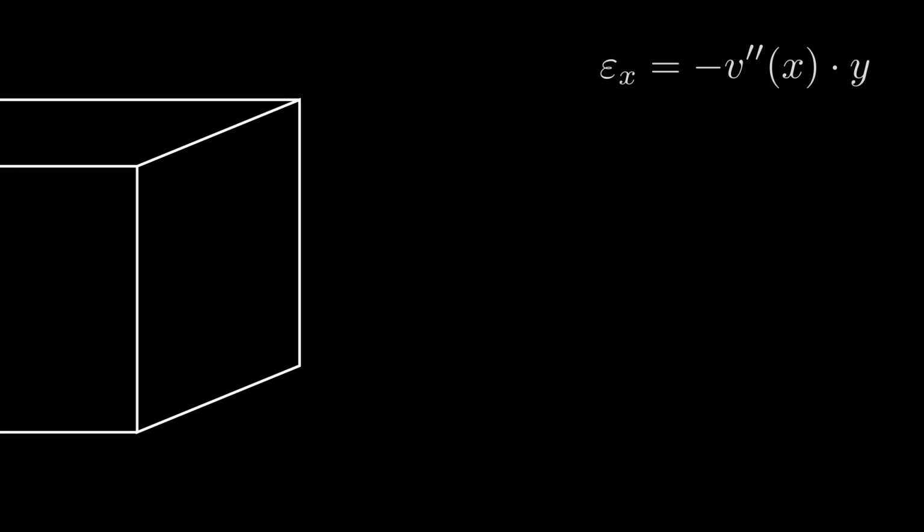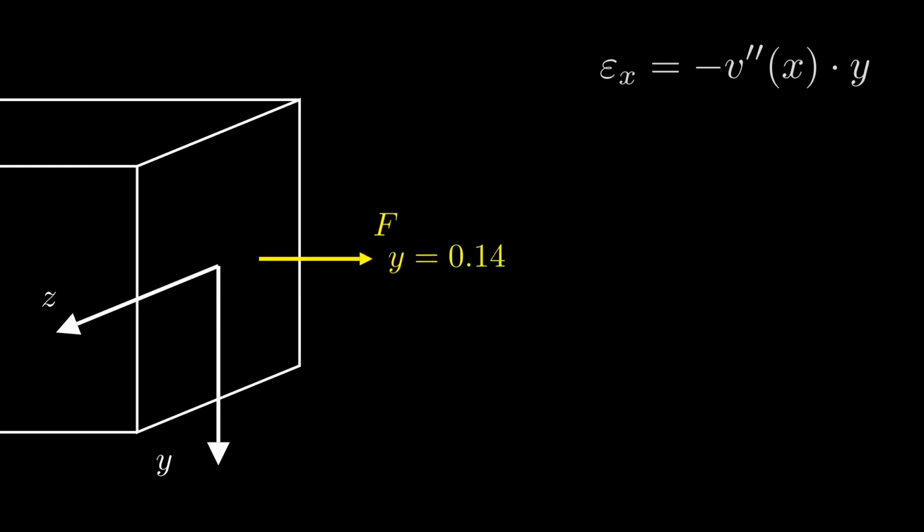According to the Euler-Bernoulli hypothesis, a plane cross-section remains plane. Consequently, if we adopt Hooke's law, the stress in the x direction will vary linearly along the y-axis. Adopting the following y and z axes, we can imagine a force differential applied at points of the cross-section as shown by the yellow arrow.